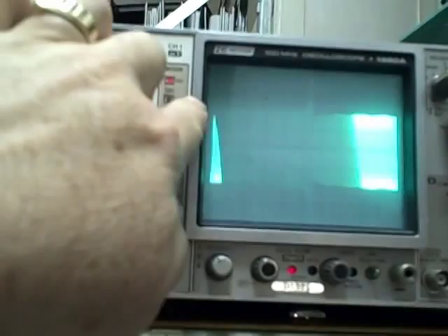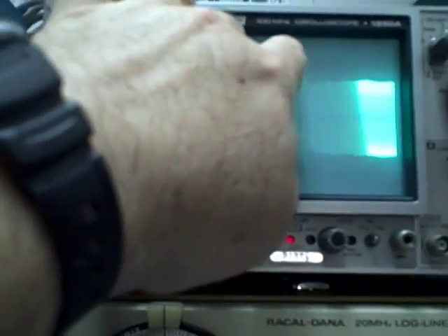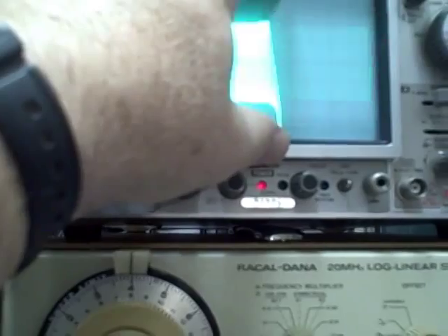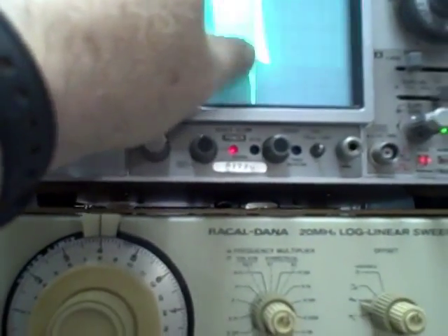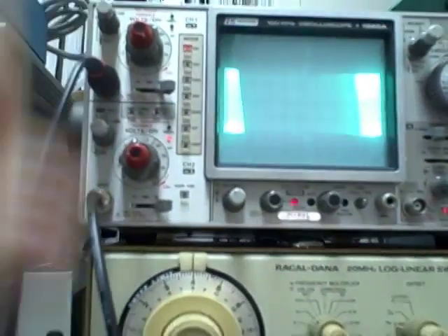And as we see, the input comes in as we're sweeping in our frequency. It's fine until we get to about 455, and then we see these dramatic spikes, top and bottom. That's where the resonator naturally resonates. And then she comes back down, and as we go forward, it flattens out again.